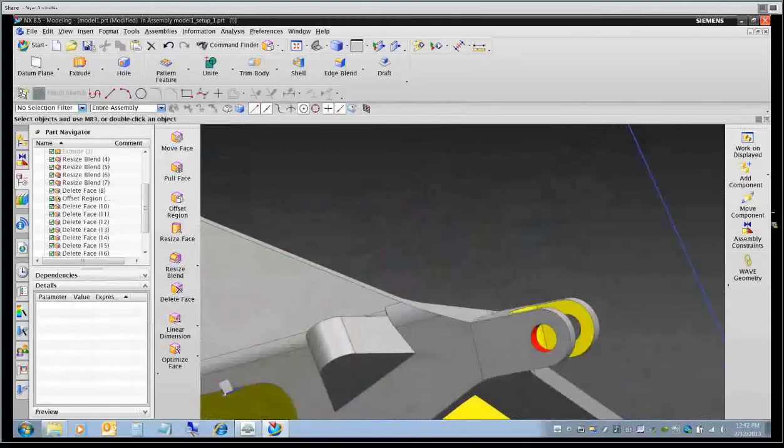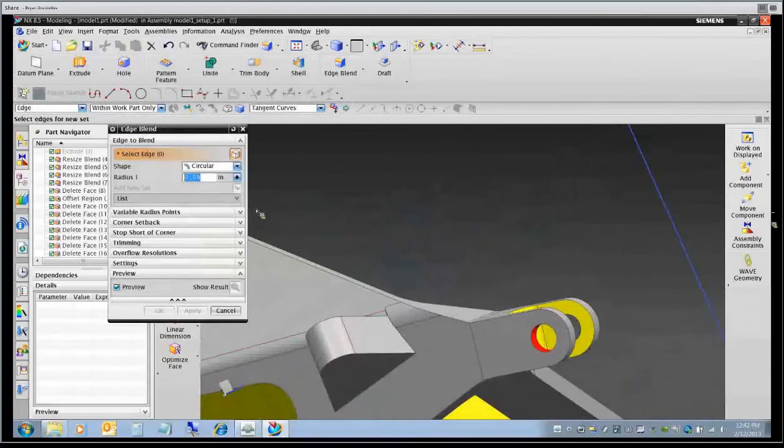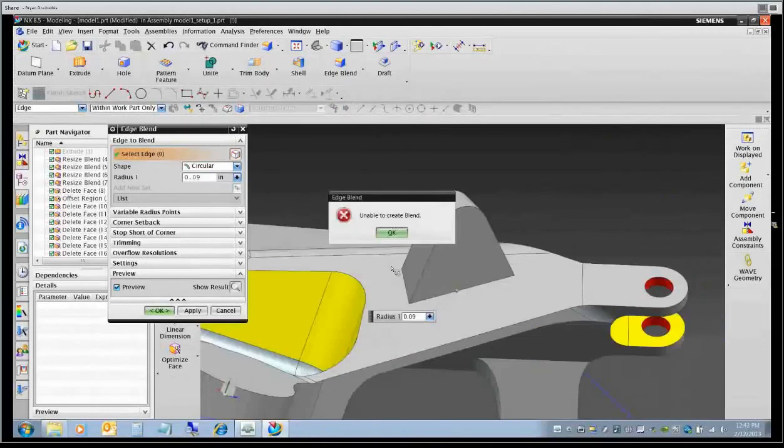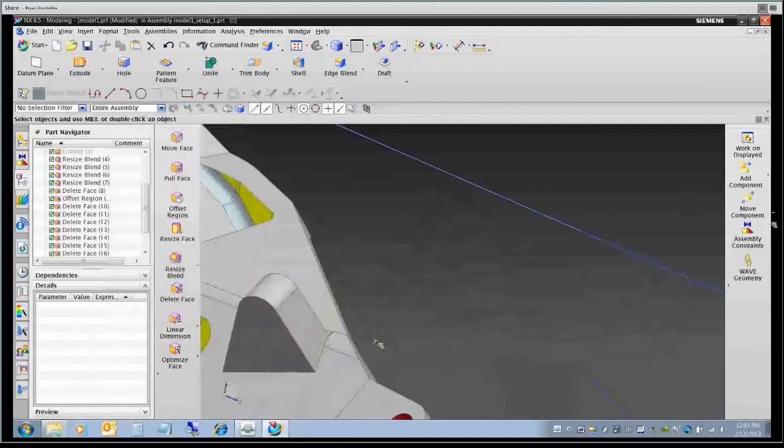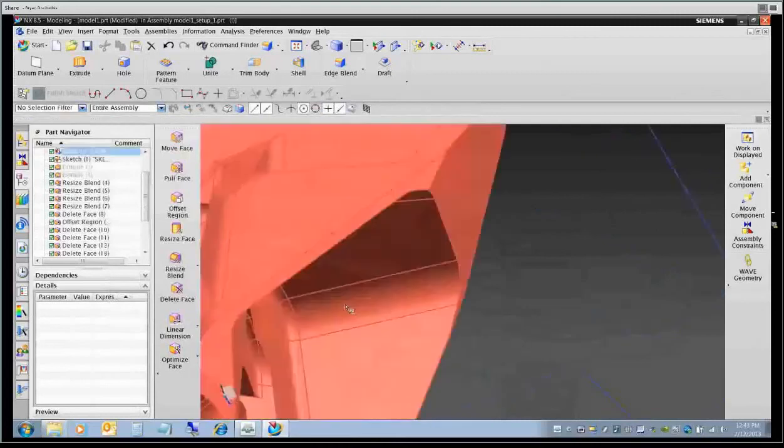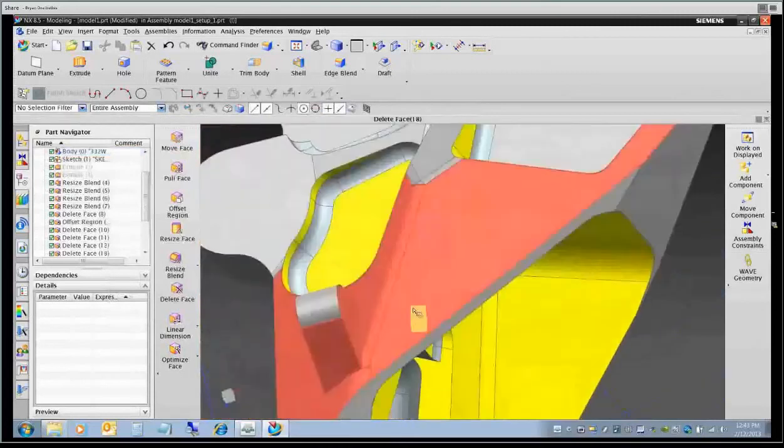From there, you could go back in and reblend this again if that had particular blend radiuses on here. Of course, this is just your standard kind of blend features. You may want to create that back as the actual casting would be. So this would give you some options to do that on the part, right? So there's our blend. Maybe we want to remove this little corner over here first. We'll blend our sharp edge off. Or the same with this edge on the offset.